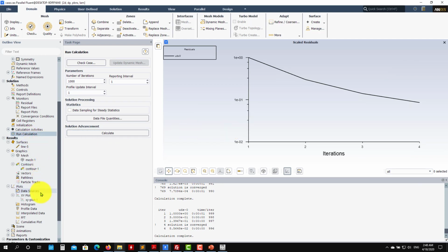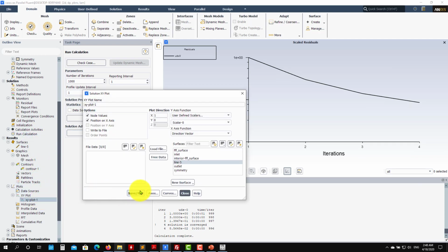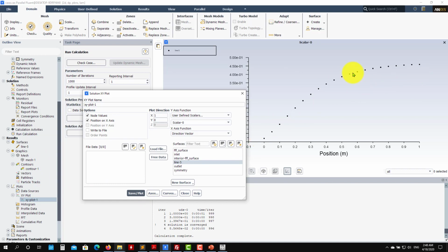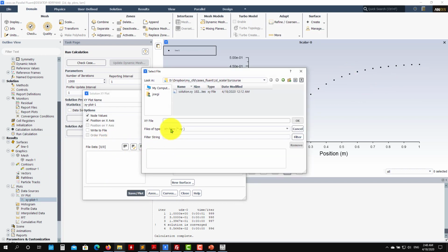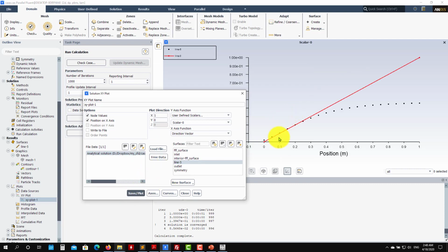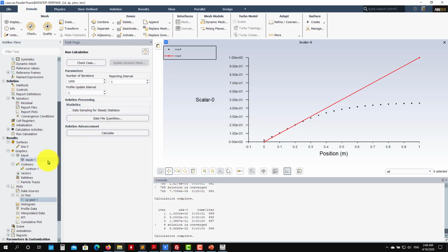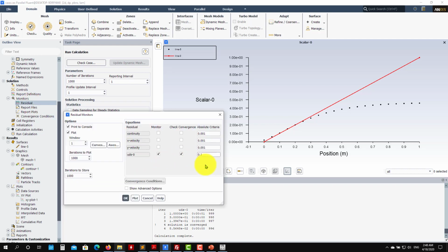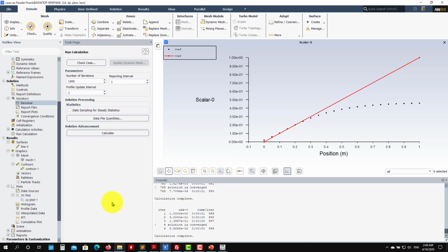Okay, 4 iterations. But if we look at the solution, see that this is an unconverged solution. Even if you reach the tolerance that you set there, that doesn't mean that you have the right solution. And that's why I say that sometimes looking at those residuals can be misleading. You need to know very well what you are doing, especially on steady simulations. So we keep reducing the tolerance here. I will go to this one. Let's see what happens.